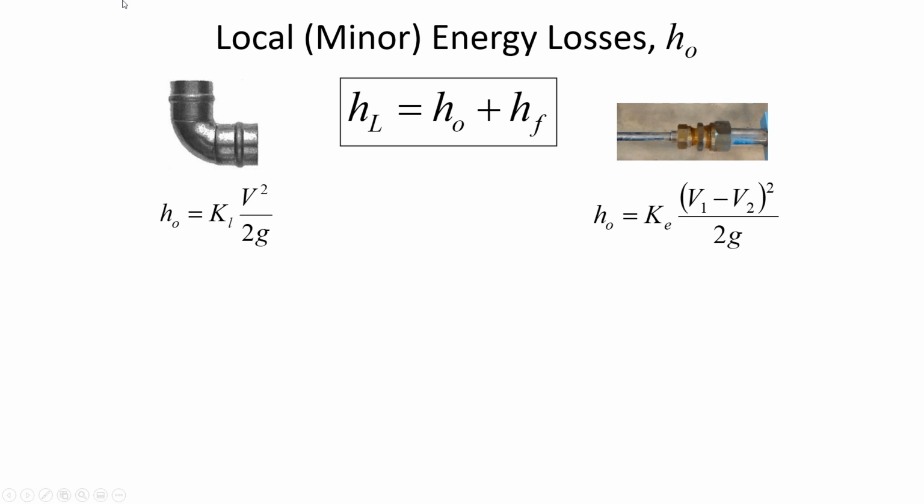And sometimes it's because of transition in the flow direction, like a bend. In other cases, it may be because of a change in diameter of the pipe that's flowing, and there's a variety of different ways to handle it. Usually, when you have a fitting that's provided by a commercial supplier, they'll also have the hydraulic characteristics of that. So if you're buying a commercial pipe bend, then the manufacturer of a valve or a bend has classified the energy loss and will give you the K value for that fitting.